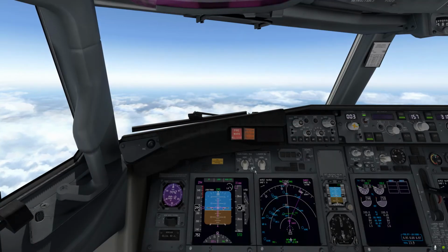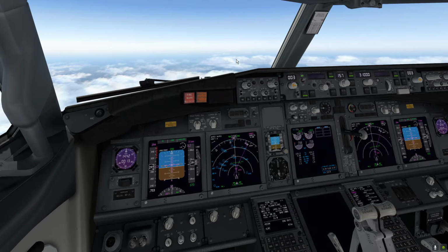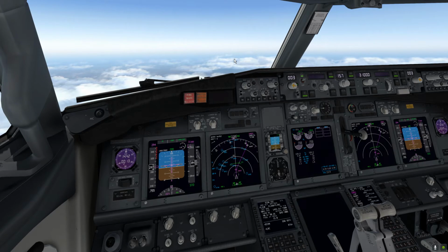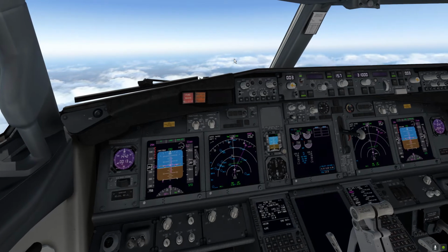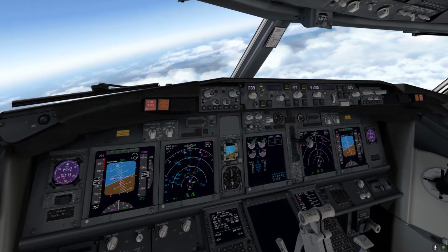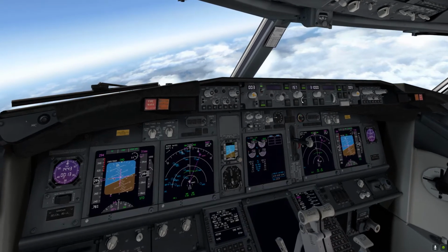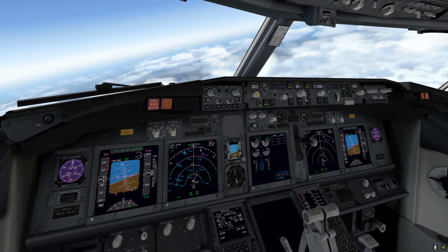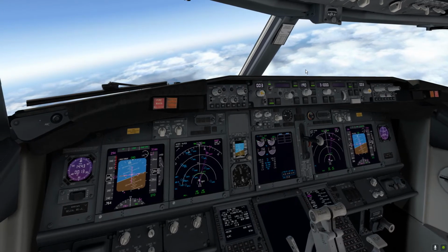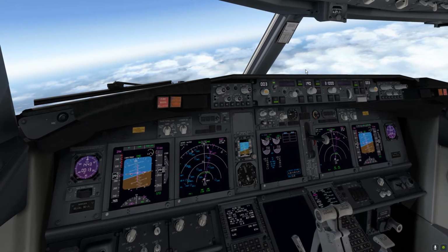Yeah, good. Let's see our climb, how it's going. Almost there. Approaching flight level 310. And then the next thing I'm doing to be ahead of the game is to cross-check the plate route with the FMC, actually, with the planned FMC route, to see if there is any point that is missed or is having the wrong altitude or speed constraint. Or something else like that.